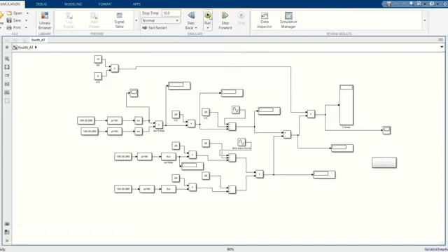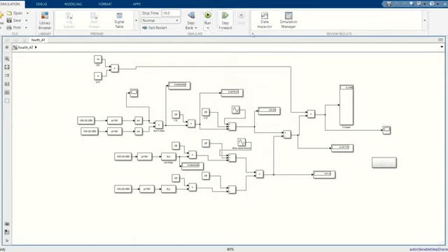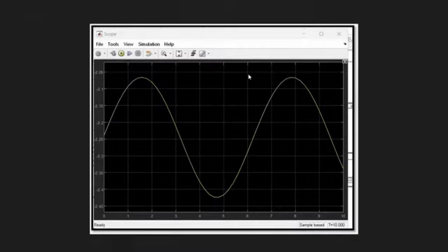Here are the results after running the simulation. The results can be displayed on the scope. These are the results of our tower shadow simulation setup. It is a graph of tower shadow disturbance versus azimuth angle. The disturbance in the wind due to tower shadow effect depends upon three factors: r, theta, and x. Hence, in the first case, r is varied from 5 meters to 20 meters, while theta is varied from 90 degrees to 270 degrees. That is the tower shadow zone.